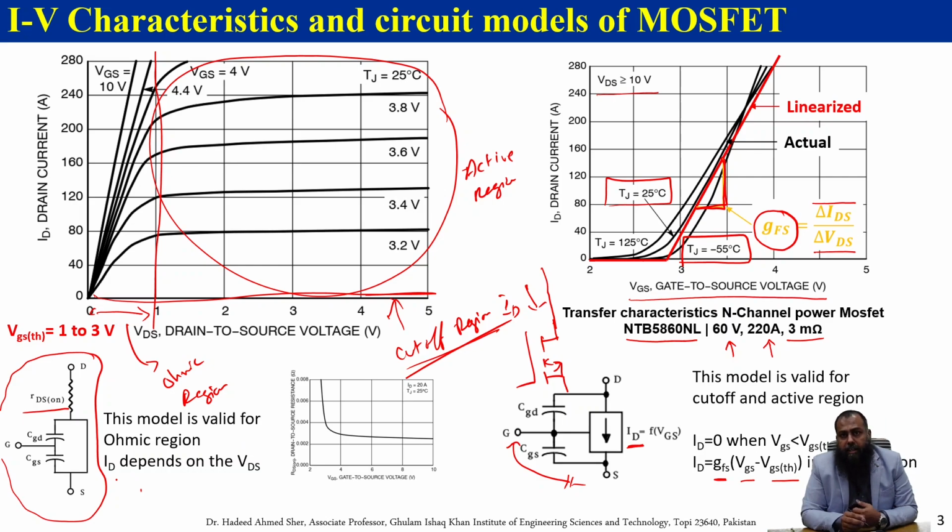And remember that the value of the drain current flowing through a given MOSFET depends on the VDS as well. So before we move ahead, let me reiterate that this RDS on is not something which is constant. However, after you exceed a value of VGS, it becomes more or less constant, thereby creating these linear regions, and thereby we call it an ohmic region here.